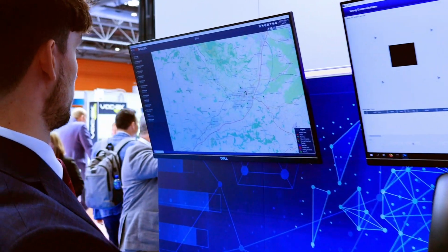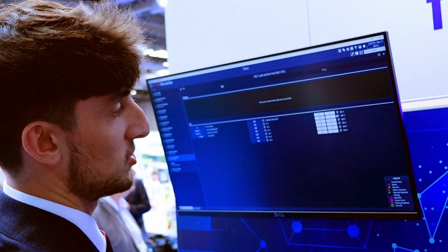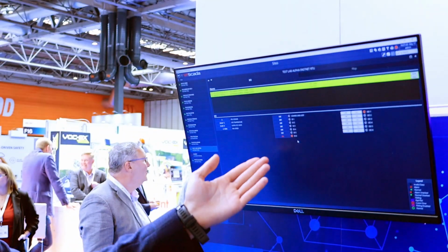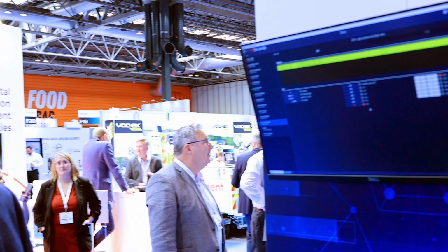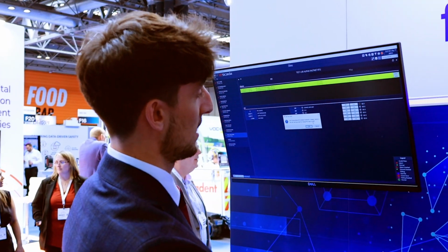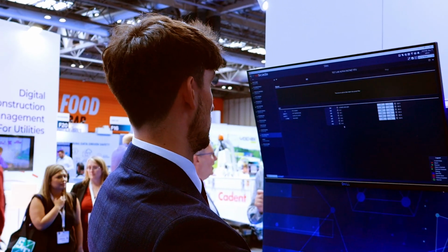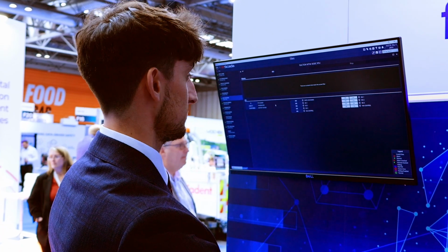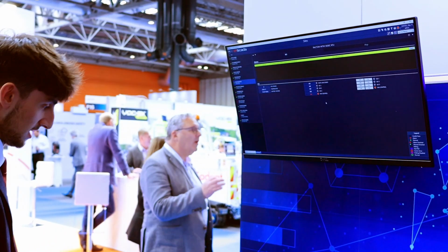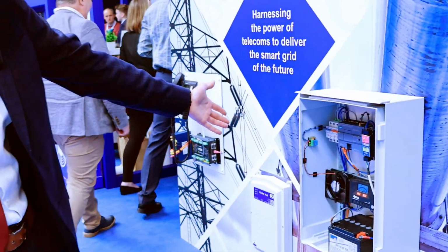So I would like to perform a function for you. So a control engineer might want to perform a digital output, which in our case we've wired it up to produce this digital input. This is going over the LTE system, over the air. There we go. And then we've got another RTU here, where simple control. As we can see now, the fan on our outstation has turned on.